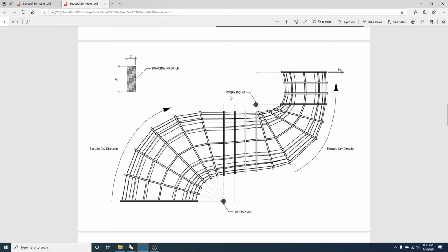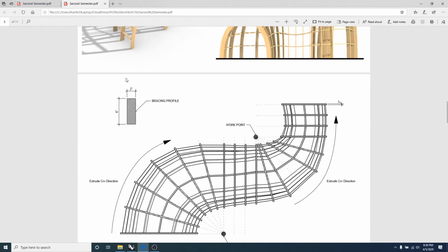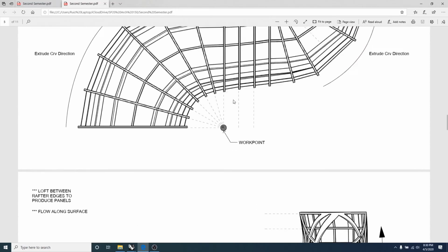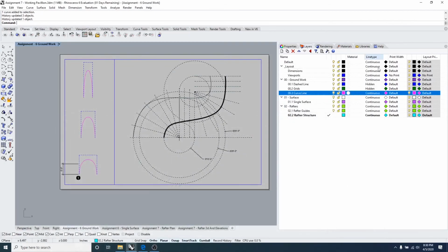We talked about how to do text, and we haven't really talked about how to achieve this hatch up here, so let's talk briefly about how to go about that. I'm just going to use this as an example. If you go into the drafting tab, you can see that we have some tools called hatches in here.